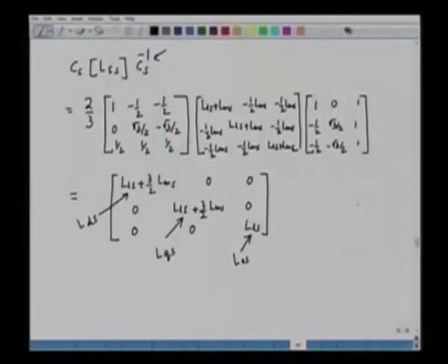So, we have seen that this is the inductance matrix of the stator in the DQ model, which does not have any off diagonal terms, and we also see that LDS equals LQS. We can say that it is equal to LS, the stator inductance of the D and Q axis, which is equal to LLS plus 3 by 2 times LMS.